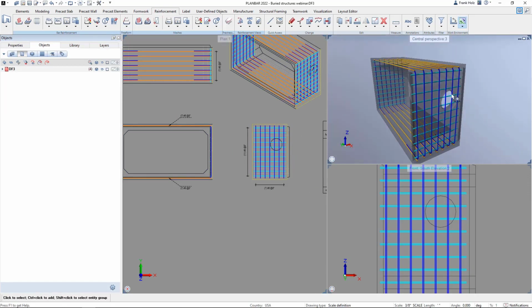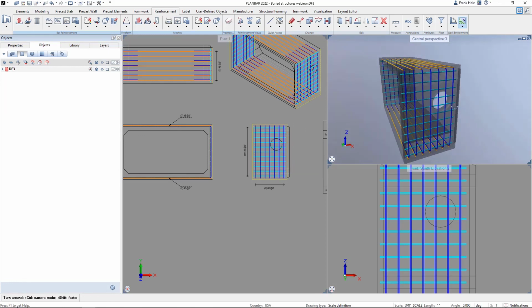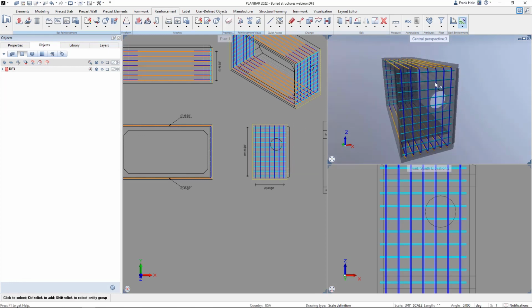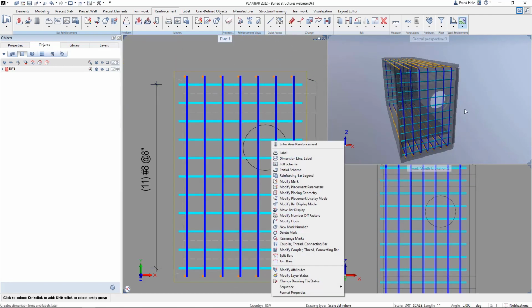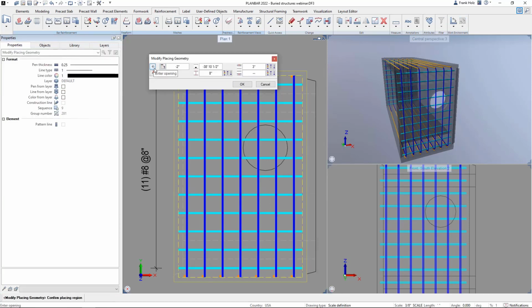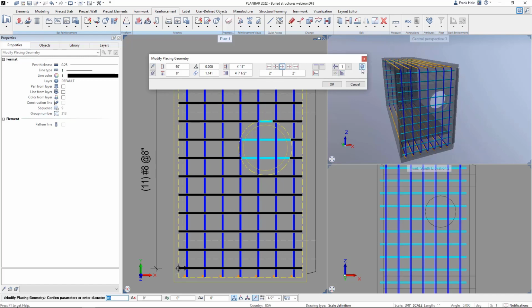All right, so first thing I did was cut the opening. We can see that the bars and the reinforcement, we can control those separately. So if we do need to keep this opening reinforced for shipping, we can do that. Usually we don't have to have the horizontal bars, so go ahead and get rid of those first. So I come back to my geometry dialog box. I'm going to say I want to enter an opening, and then I'm going to use my area detection tool. This is great for all kinds of shapes of openings. You simply just select in that area, it finds that opening.